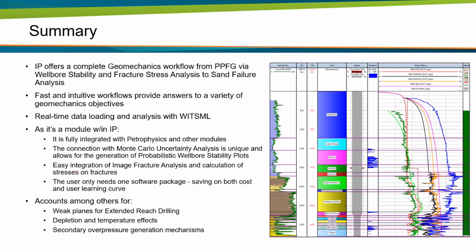All right, so that's it. Summarizing, we have seen a lot. You can do pore pressure prediction, fracture gradient analysis in IP. You can do wellbore stability, sand failure analysis, and analyze stresses on fractures. The workflows in IP are supposed to be fast and intuitive. If for some reason you are using IP and you think it's not so intuitive, let us know and I will take note of it and we will improve the workflows. But they are definitely interactive.